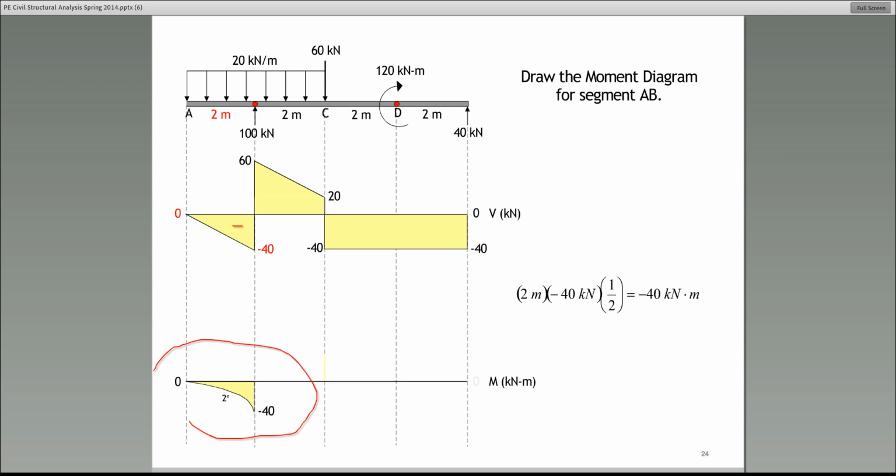It's a second degree curve with a negative slope. All right. But on the test, they will ask you one other thing. Yeah, Ryan and Alan, the shear force diagram will always have to close. If it doesn't, there is something that you've done wrong.